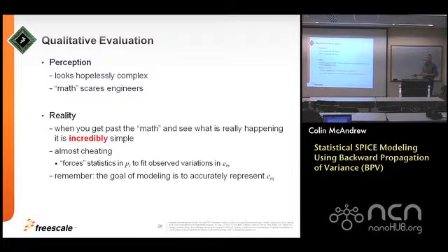But you want these model parameters P to be very physical. Yes. You want to go back to the manufacturing person and say, I need better control of this P. Yeah, the manufacturing people know what to do anyway. I don't think we've ever fed anything back from a set of models to them. We do use these to understand where circuit sensitivities are. If a part fails or over years all of a sudden the yield drops out, we'll do that. But the fab engineers know what knobs to check. They have their metrics and track them.